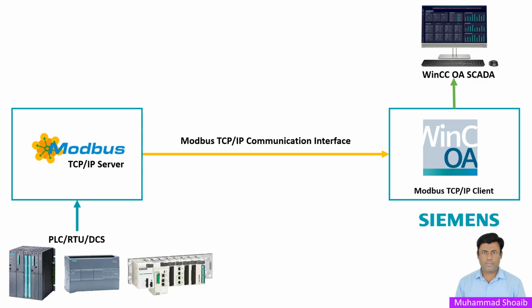Before we jump to the configuration, let's quickly understand what Modbus TCP is. Modbus TCP is one of the most common industrial communication protocols used for connecting devices like PLCs, PCs, RTUs, sensors, or any third-party SCADA systems. Modbus TCP is a client-server protocol that runs over Ethernet.